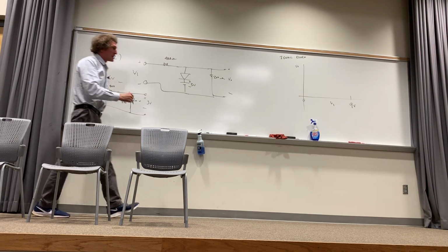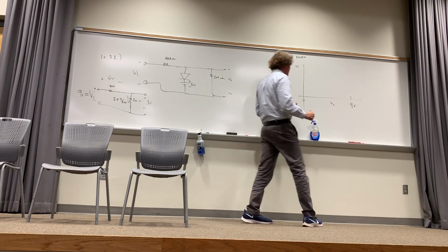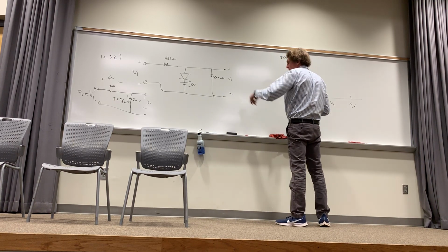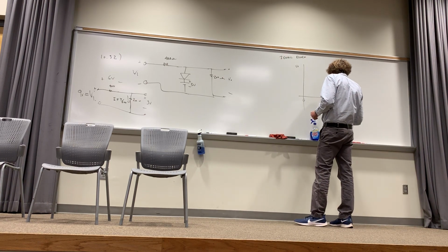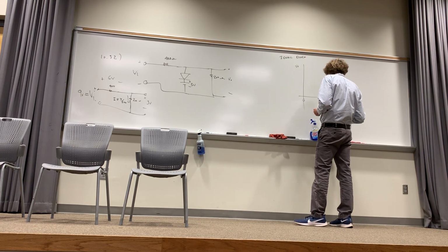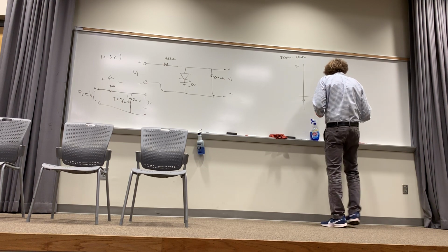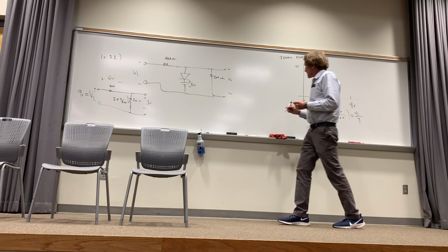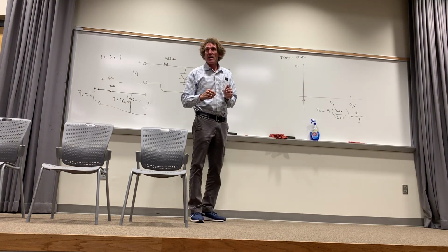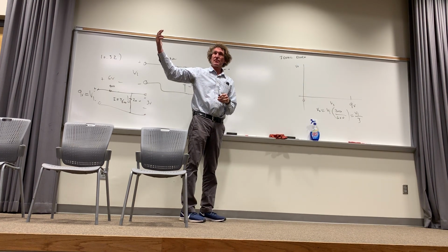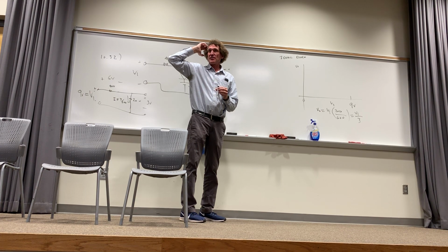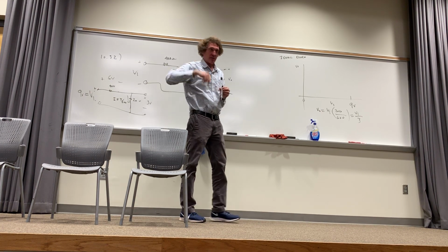So now I can say until we hit 9 volts, Vout will be equal to Vin times 200 over 200 plus 400, or 600, or it's really Vin over 3. Everybody got that? This is all the way up until the input voltage hits 9 volts. Do you all see this, class? Give me a show of hands. I've got to make sure you see this. This stuff will confuse you if you're not clearly thinking.